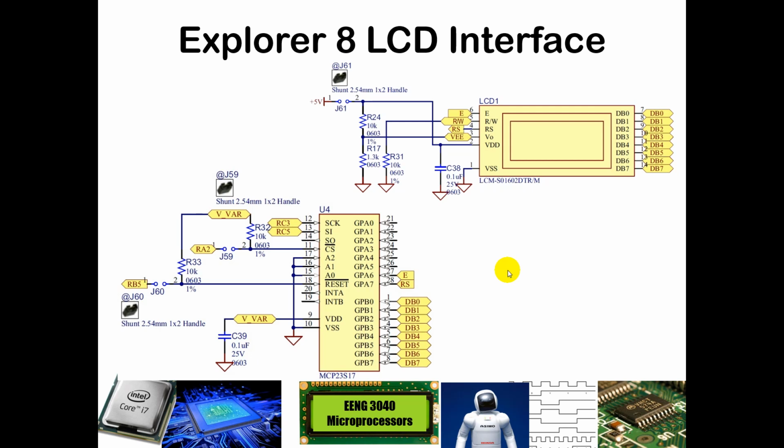Certainly with a 40-pin microcontroller, we could directly control E, RS, RW, and the data lines. And in fact, in previous semesters when I used a different trainer board with this class, that was exactly what we did. We used some pins on port A to control E, RS, and RW, and then we used port D to control the data.